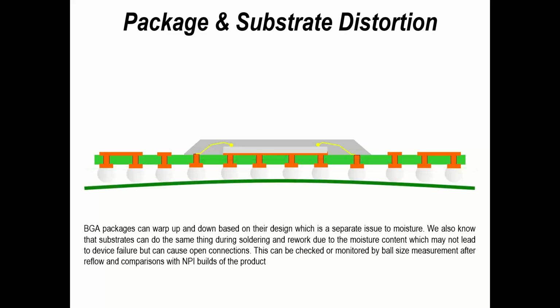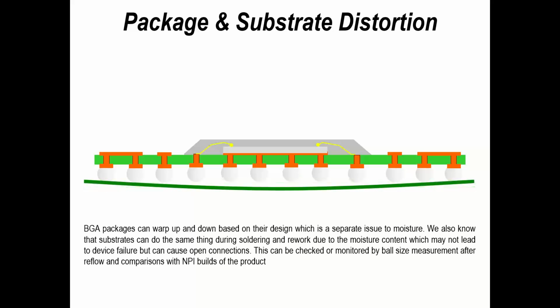Now, not only does moisture content affect the board and components during these operations, but again, it can cause the board to flex and move and expand and contract. So sometimes you might find on ultra fine pitch assemblies on larger boards that the positional accuracy of the component and the board pads change because of moisture content.